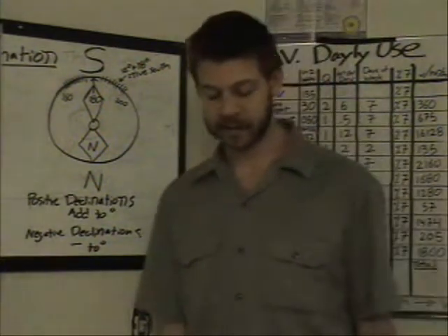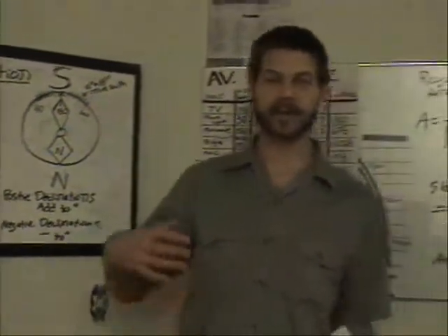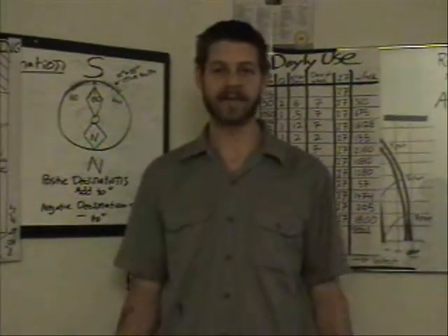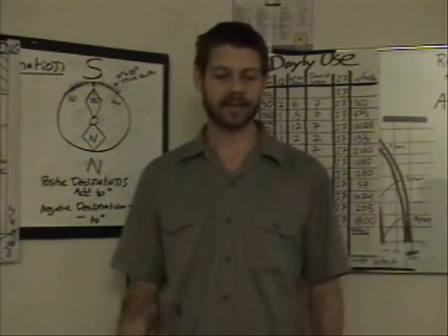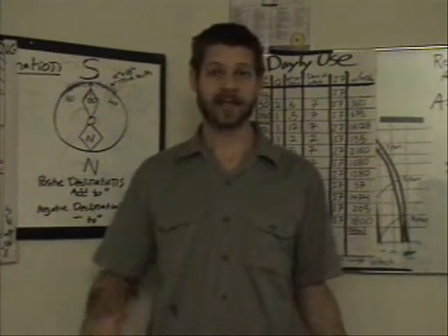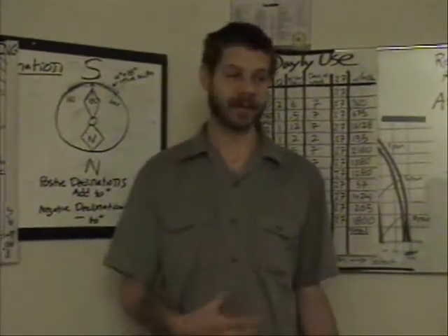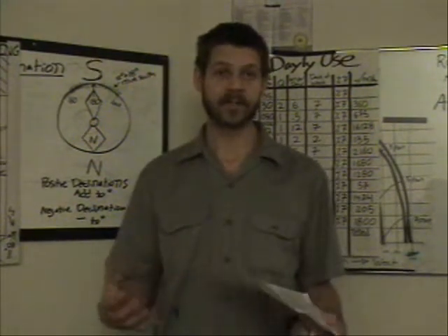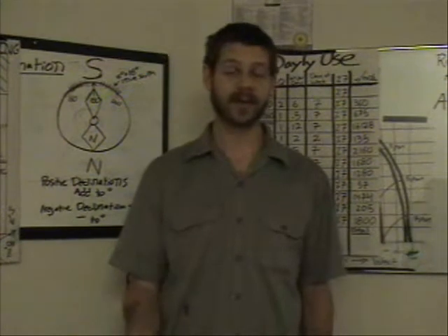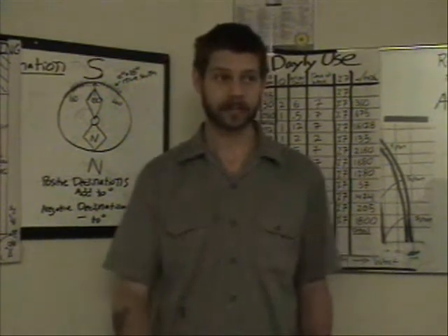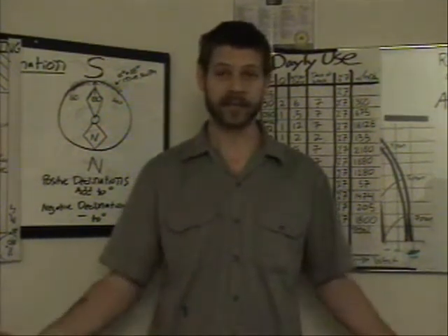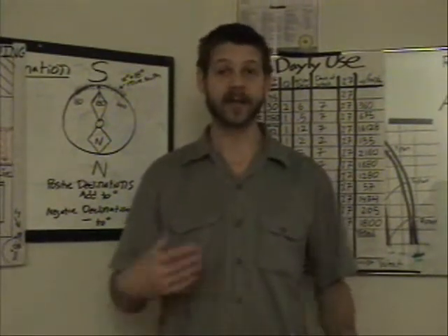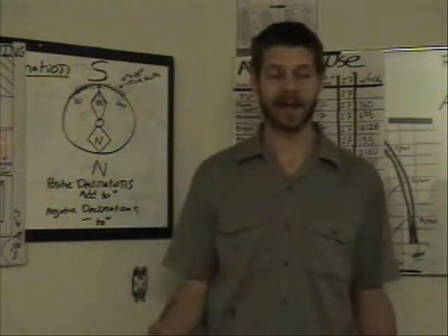The next thing we're going to have to talk about, the two things needed to really determine the size of an array, the size you're capable of having and the size you need, is the load requirement. Every house has a load requirement. Everything you have in your house that's electric draws a load. And you need to determine what that load is. The best and easiest way to do this is you take your power bill for the last couple of years, you add it up, and month by month you get your average daily load, just simple averaging.